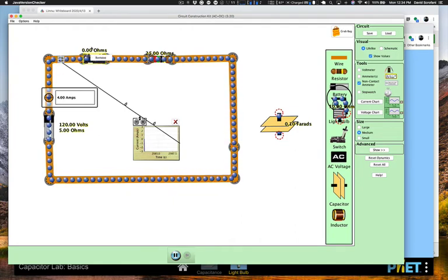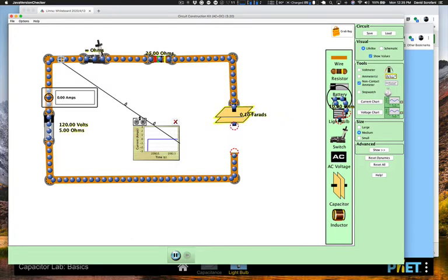Okay, so what the capacitor really does is it introduces some time variation into this circuit. It says, yeah, your current can be 4 amps, but just initially, and then we're going to drop, asymptotically approaching 0. Now, there are mathematical functions that model this behavior, and they can be obtained by solving a differential equation that you write for the circuit, and we're going to do that in a follow-up tutorial, but we don't need to look at that just now. Okay?